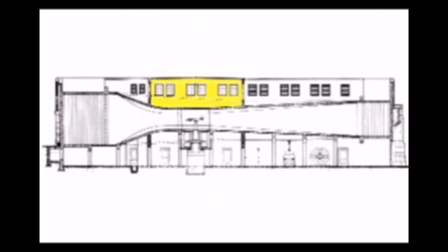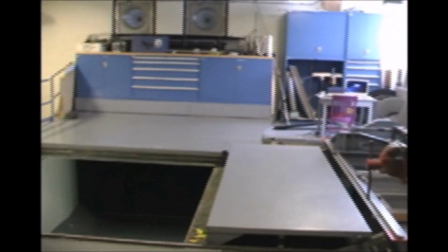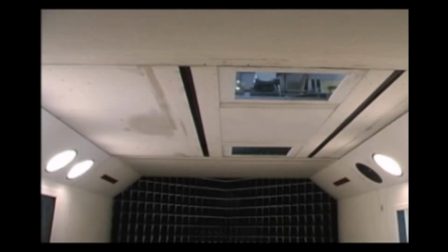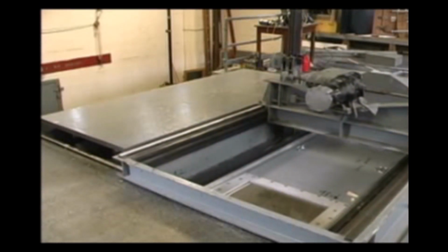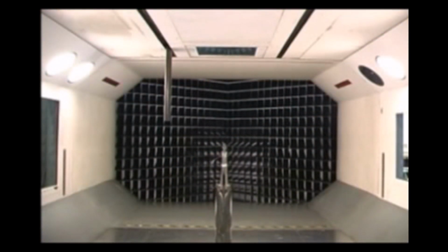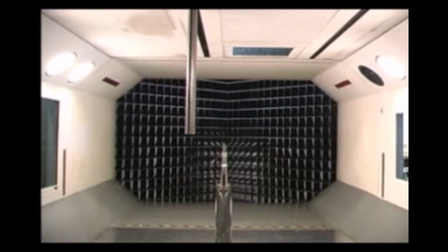The traverse deck is located directly above the test section and contains much of the hardware for flow visualization processes. The test section ceiling is on tracks and can be moved sideways across the tunnel by an electric motor. The carriage located on the test section ceiling supports 2 struts which can be driven on vertical tracks. This allows for accurate 3-axis positioning anywhere in the test section of probes mounted to the end of these struts.